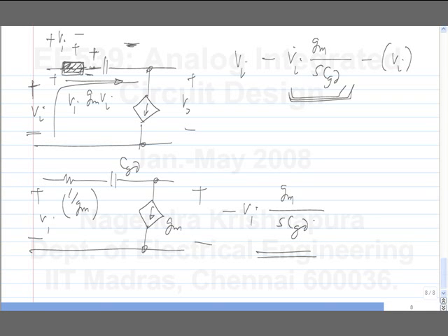I mean, this is some vague analysis of a bare bone circuit that does not represent a real common source amplifier. But you analyze this, and then the other interesting thing is you see what happens if I connect all of the stuff. Okay. You do the full analysis, including, let's say, the output load. For simplicity, you just first put one element, just the output load, and then see what happens. What else can you do? Yeah, think about other ways, the idea is the same always. Somehow you have this set of equations, maybe you get rid of some term or something of the sort.